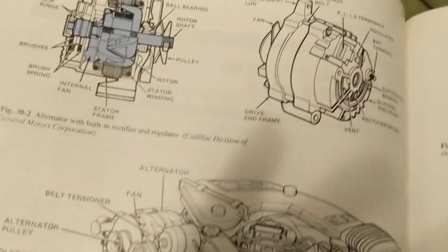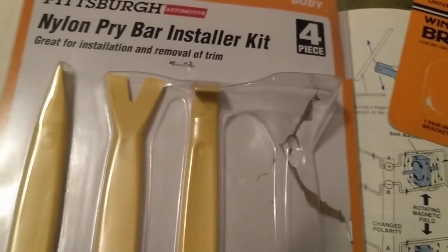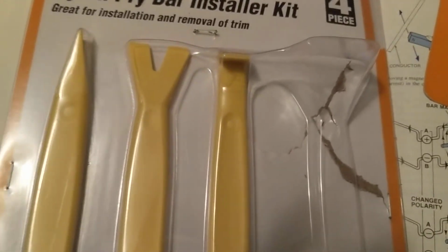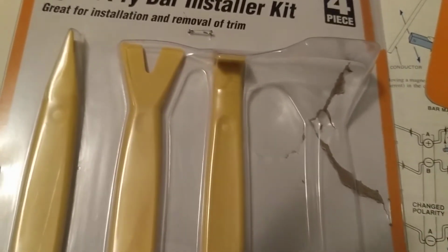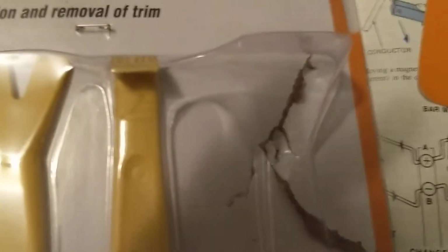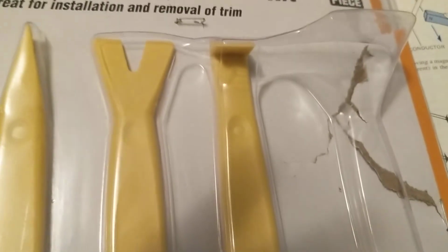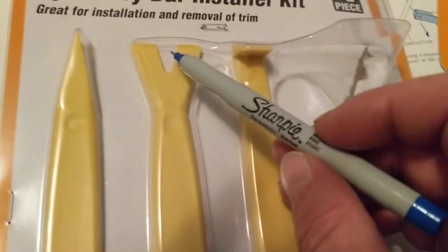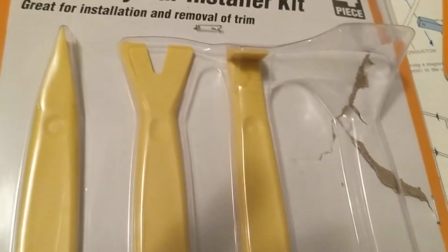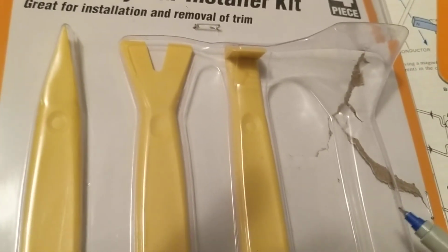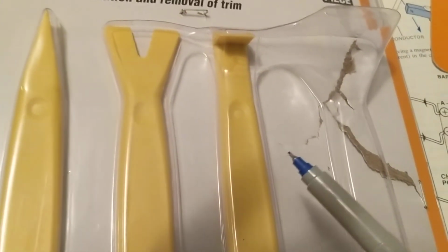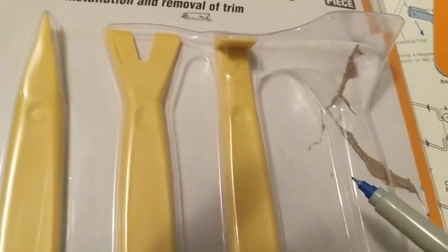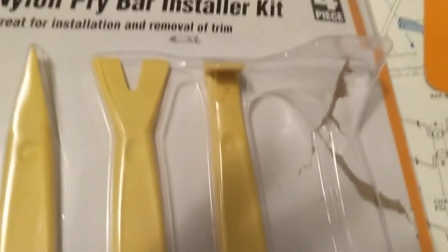Now, a couple of tools that I wanted to stress. There are some tools that you can pick up, and they're very cheap, for taking out the panel, of course, the dashboard and all that. You don't want to use metal, because metal will scratch things. So it's better to use plastic. These are very cheap tools that you get, especially this one. And there's another one that I took out. These are very cheap, less than $10 for sure. And you can use it to pry up the dashboard panel to get underneath it.